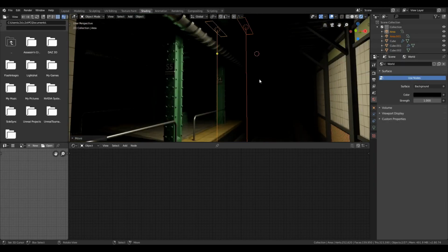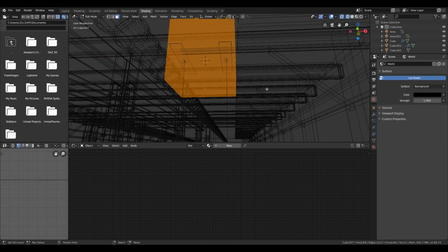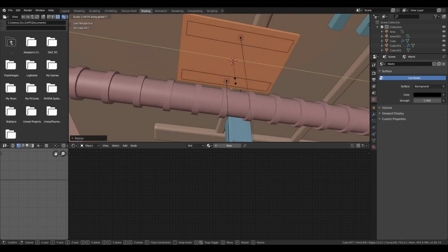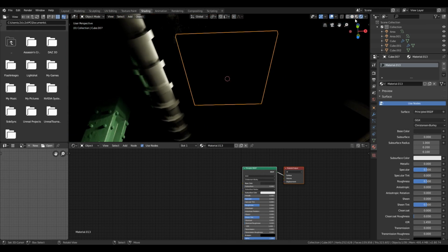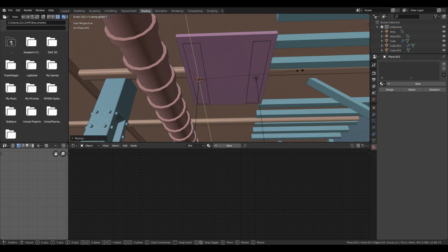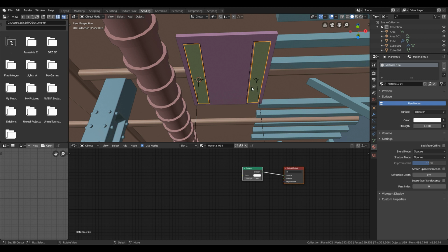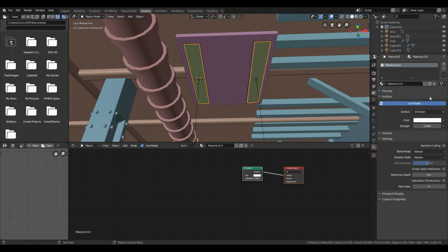Now go to the render tab and change the world settings color to black. To avoid the light hitting the roof, we just need a box over the area lights and assign black color to it. Now put the cursor to the center of the lights and try to cover it with a mesh plane to create a source light. Assign an emissive material to the mesh.